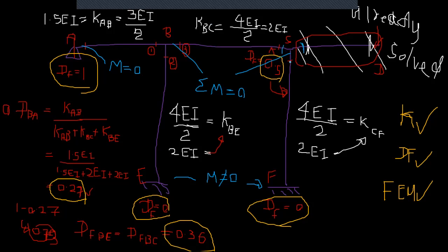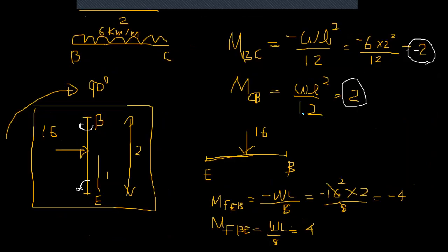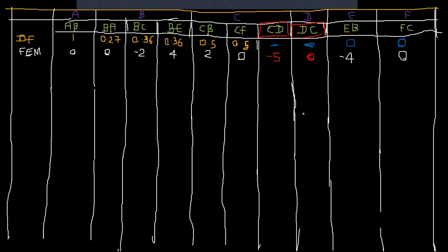So the remaining 2 halves: if this is minus x, and this is minus x, the addition of these two bending moments should be exactly plus x. That will happen automatically once you solve this.